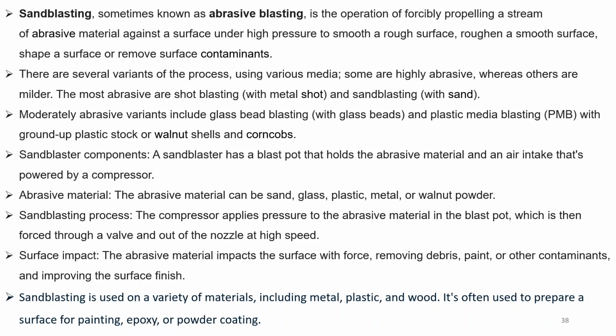Some are roughly abrasive, whereas others are milder. The most abrasive are shot blasting with metal shot and sand blasting with sand. Moderately abrasive variants include glass bead blasting with glass beads and plastic media blasting, known as PMB, with ground up plastic stock or walnut shells and corn cobs.